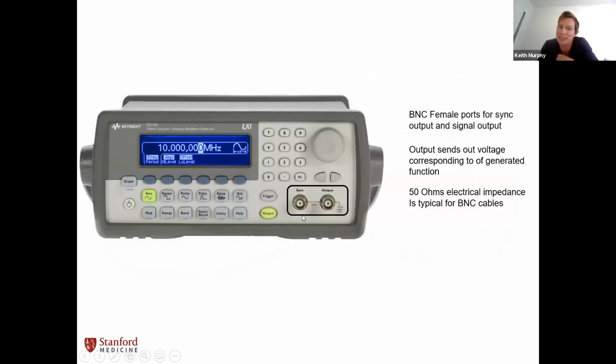And this cable is just a common interface to connect equipment. I think these were developed around radio frequency labs, but people use them in ultrasound very commonly to get a coax, positive and negative. Here I think the positive is the inside and the negative is the outer ring. And you can connect various tools. These are very common to function generators and other systems.